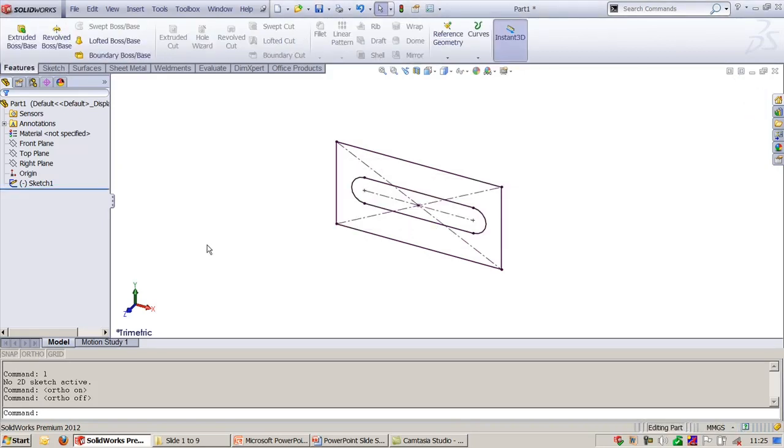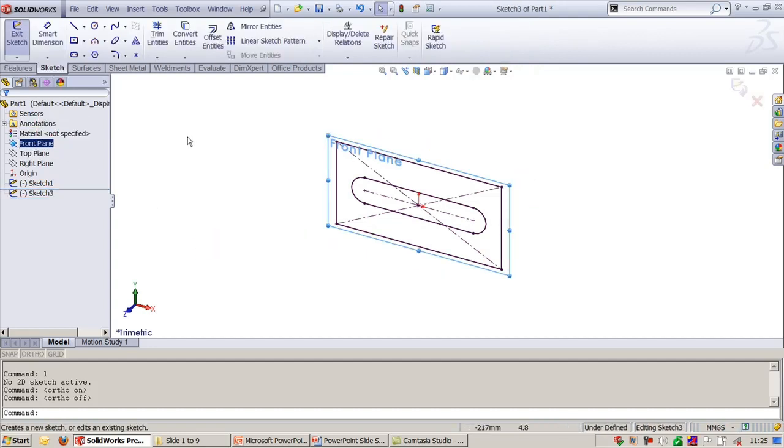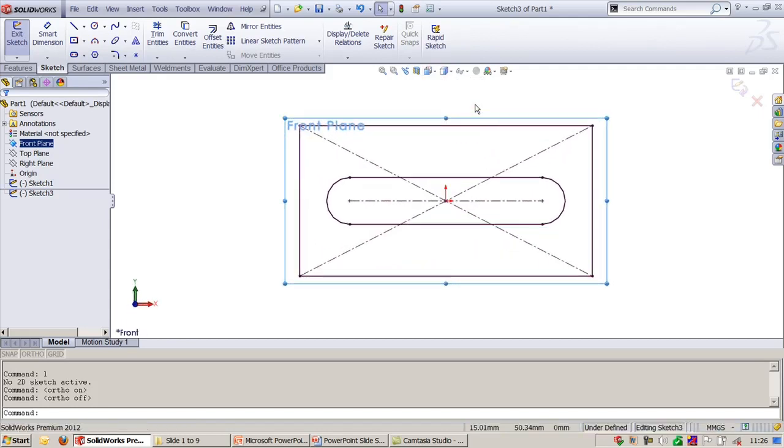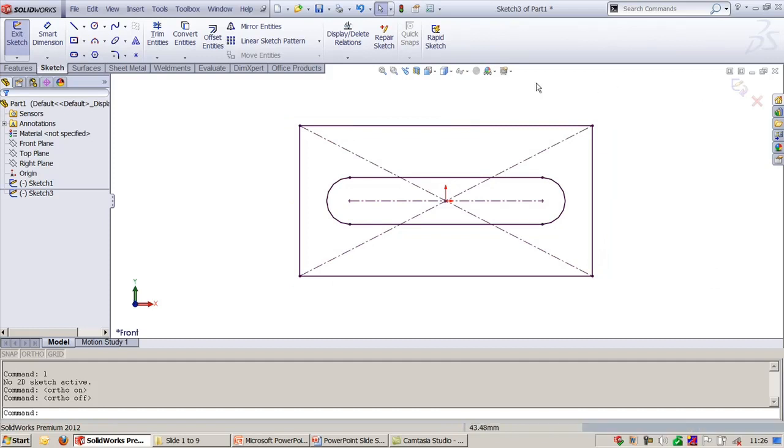And now the next step, I need to create a sketch. I'll go to the front plane, use this callout and use sketch. And after this I'll go to one more flyout toolbar. Here I will use normal to view, and once you do this, you need to go to any one of the commands from this command manager, and I will select this line and you can draw this. This is by choosing the icon, or if I want to follow the AutoCAD methodology of typing the command here, I can say L, enter, and from a point, where you don't want to use the cursor once again, I can type 0,0 and enter.